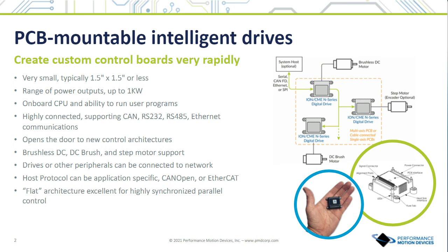acts like a 4-axis system, and there's an expansion network on the back end, and all the smarts are in the drive. So the host sends all the commands to the first drive, and that does the translation from the host protocol to the local PMD protocol, and you get seamless synchronization across the axes, which is something we're seeing a lot of, where they want very coordinated motion and all the axes acting in synchronicity. And this kind of gets you to that.